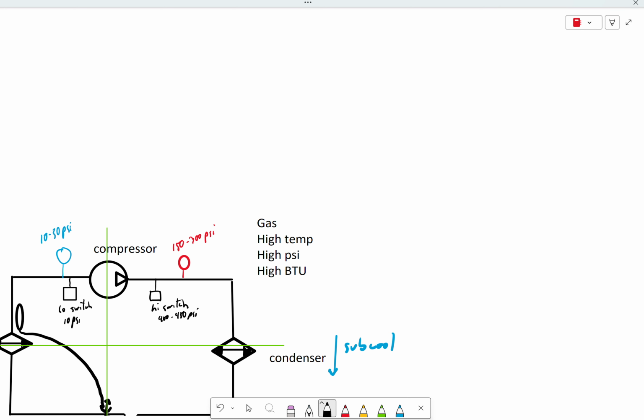All right. If you do decide eventually that the gravy work that air conditioning work is might be something you'd want to make part of your regular duties, get yourself a decent set of gauges. And the ones that you're going to want to get are going to have 4 hoses and 4 knobs on them. They do cost a little bit more, but honestly, if you start doing a fair amount of AC, you'd really appreciate having the options that setup gives you.